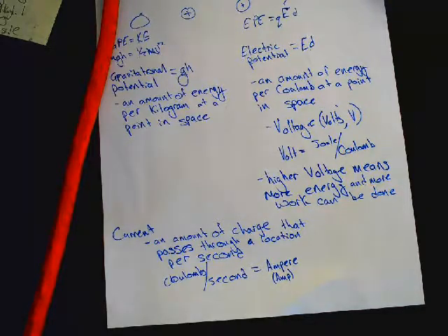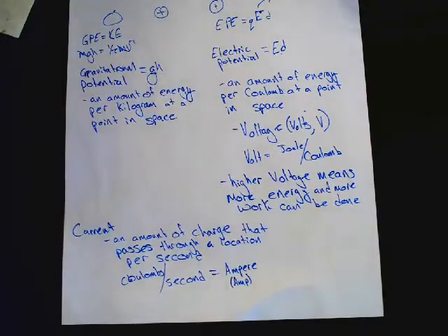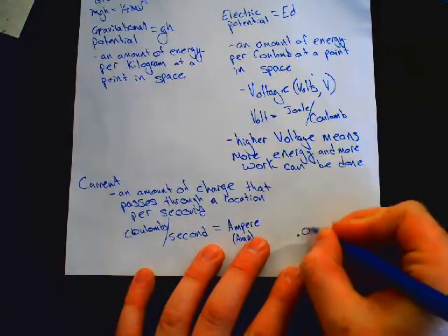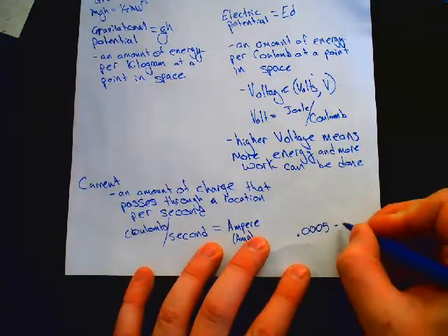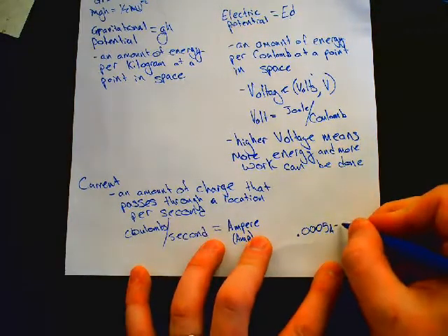Again, this one's running at 15,000 volts. The dangerous part is that it runs at 0.3 amps. To give you some idea of scale there, I'm going to try to get my numbers right here. 0.0005 amps is a slight tingle. That's when you can kind of feel it.